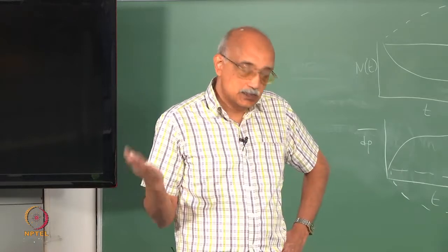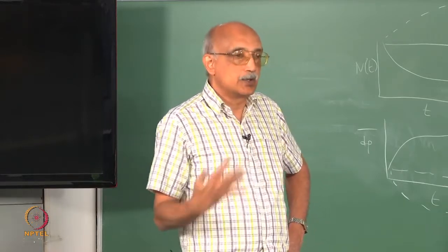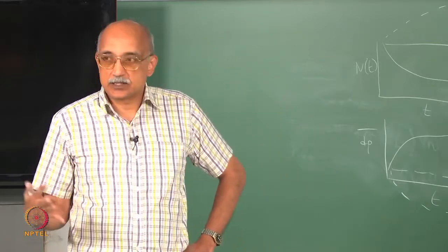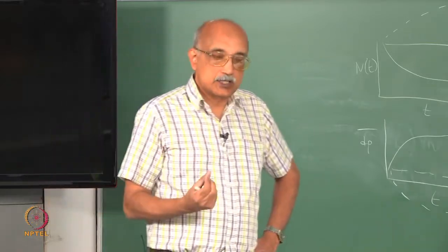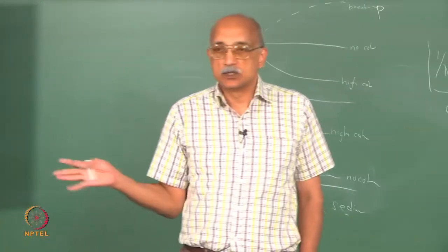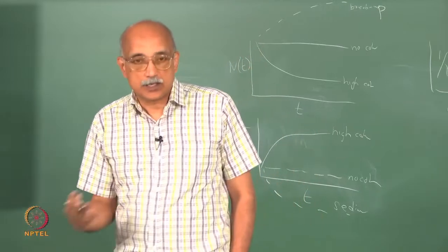Mu is the viscosity. The less viscous a fluid is, the more likely that cohesion will happen. Again, once you have thought about this in terms of mobility, that makes sense. If you have a less viscous fluid, there is less resistance to particles moving around. So, they are likely to move around more, find their nearest neighbor and attach themselves.